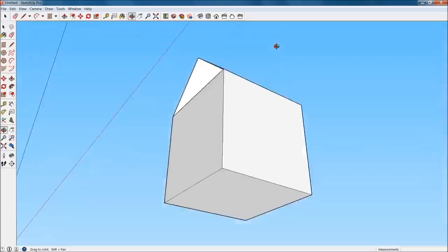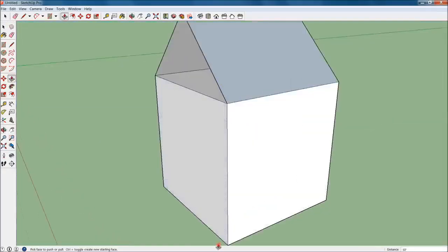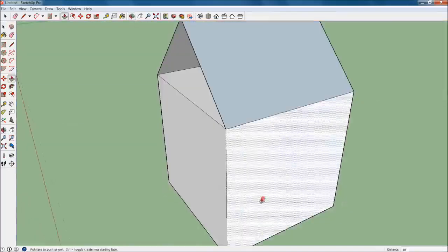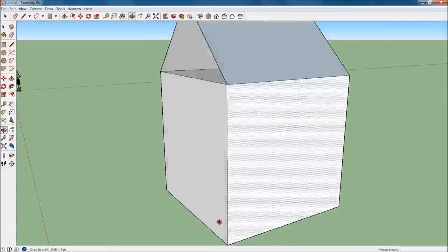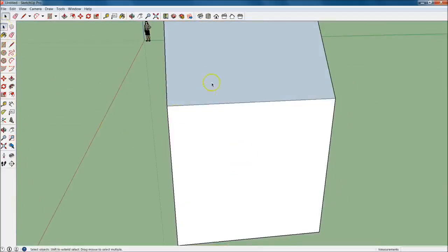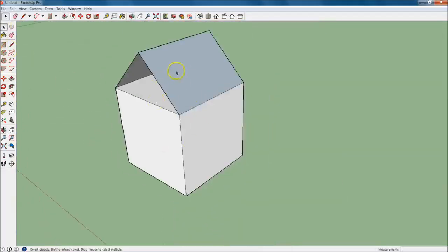So in SketchUp, there's really no material applied right now, but the default is to have this white with this light blue on the back side. Let's skip that part actually. We're going to undo that real quick with Control Z, and we're going to do the push-pull tool right there. As we're pulling back like this, you'll see that it goes blue, right? I want you to just hit Control. Did you see that? I just hit Control. Now on the Mac it'll be Command. If not, somebody comment and say it's not, but you're just going to pull it back and then drop it on that point right there.